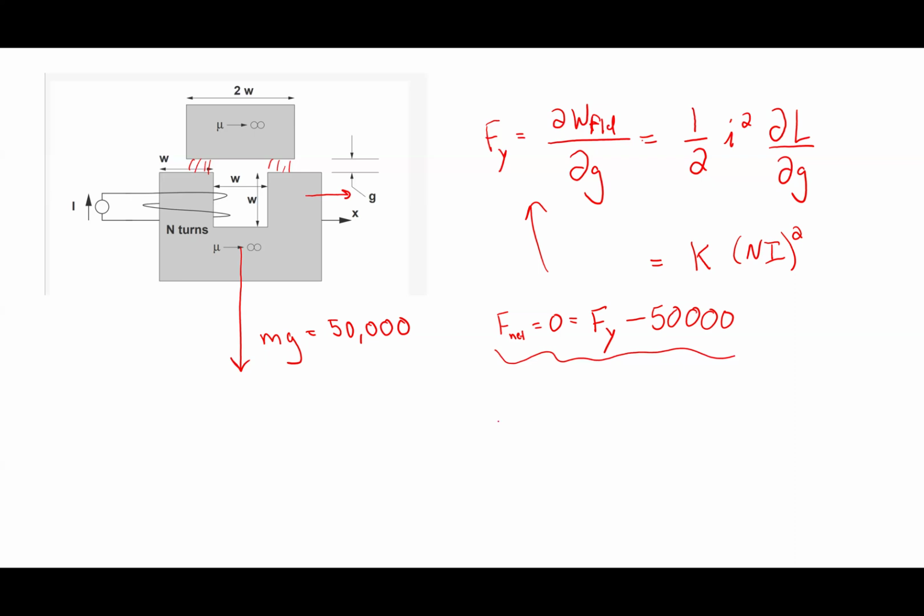In the last part of the problem, it says there's also an X direction force, which would be the partial derivative of the energy with respect to X. The nice thing about that force is there is no applied force in this case. In other words, there's no force in the X direction, unlike in the first part, where there's the force of the weight of this thing.